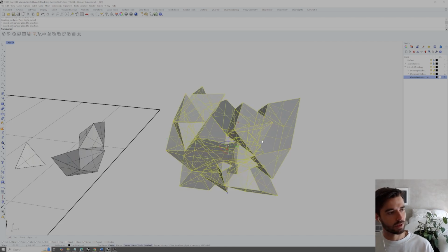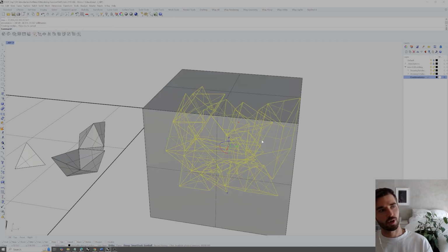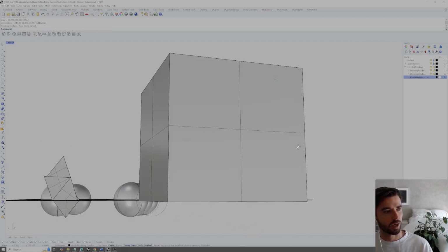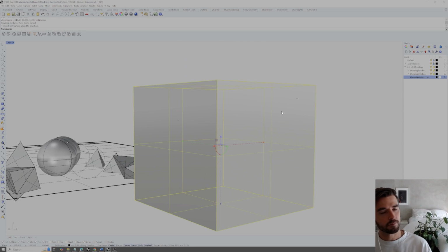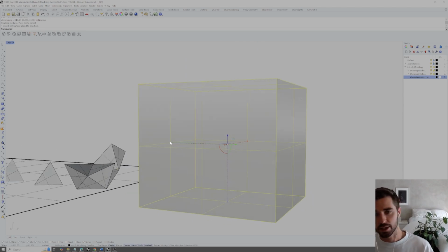And before we get into the cone, I'm actually going to draw out a bounding box around these volumes, shrink it a little bit so that we first start with a bounding box alignment. So with it selected, type bounding box. This is going to draw out a box around the entire geometry with everything contained. Select that box, hit Shift and then click on one of these small boxes on the gumball.